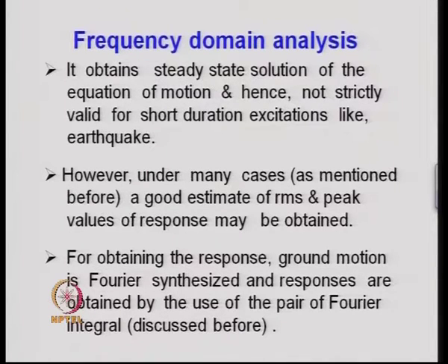And therefore, for short duration excitations like earthquake or any other impulse kind of loading, which is a short duration loading, the frequency domain solution may not be applicable, that is the steady state solution there does not represent the true response of the structure.